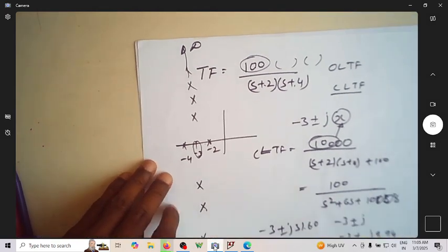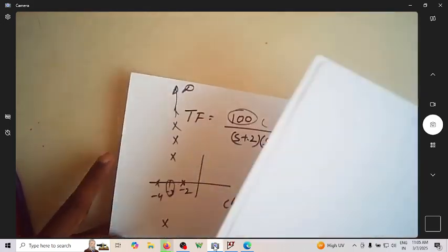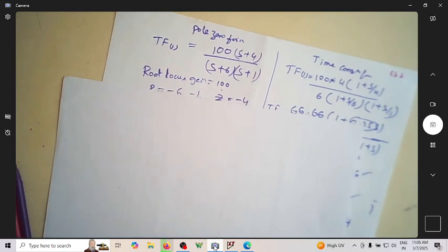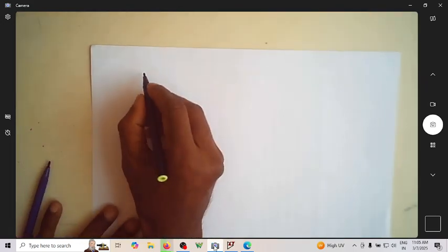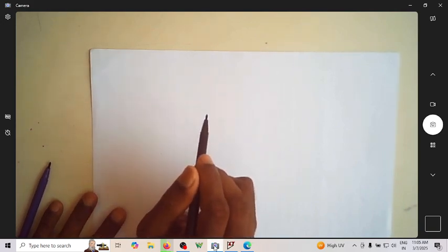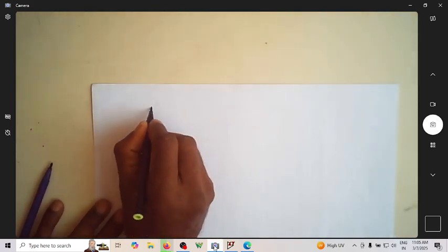Now, why are we so worried about this closed loop pole position? What is the reason behind worrying so much about the pole position, whether it is at infinity and so on? We will also see one more interesting thing: if a zero lies on the right hand side of the S plane, what happens. I was saying that an open loop pole will go towards the zero wherever the zero is sitting. So let me take this transfer function.